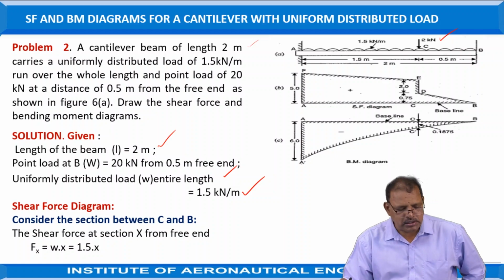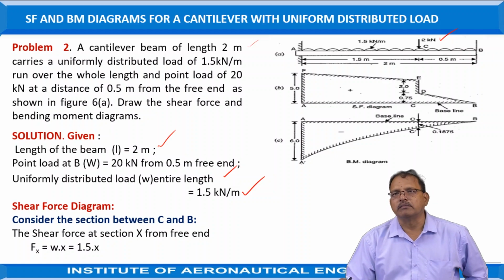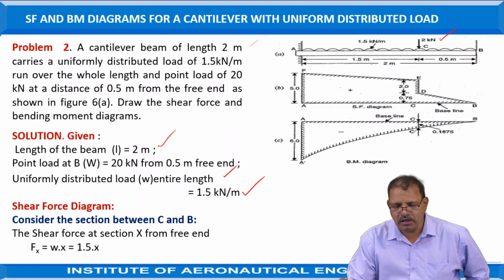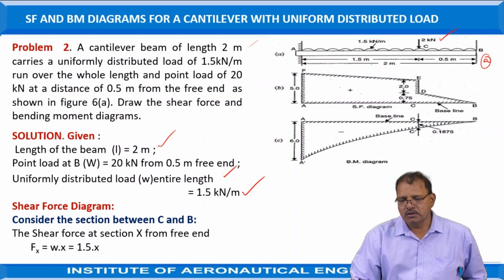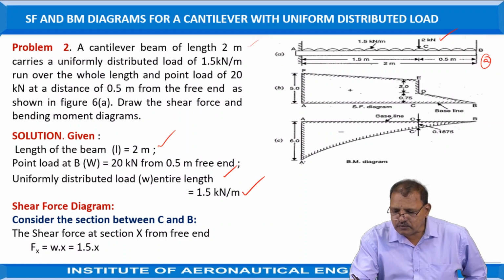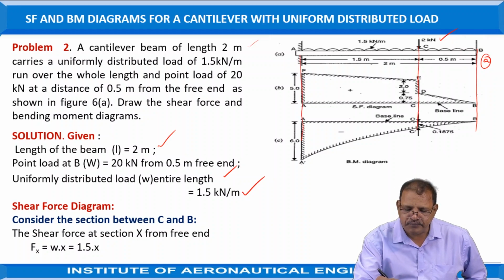First, we have to draw the shear force diagram. First, draw the beam according to a suitable scale and represent the forces which are acting on it, as shown in here. Now, in order to draw the shear force diagram, first of all, draw the vertical lines in 4 directions which are passing through the important key points, as shown in the figure, like this.